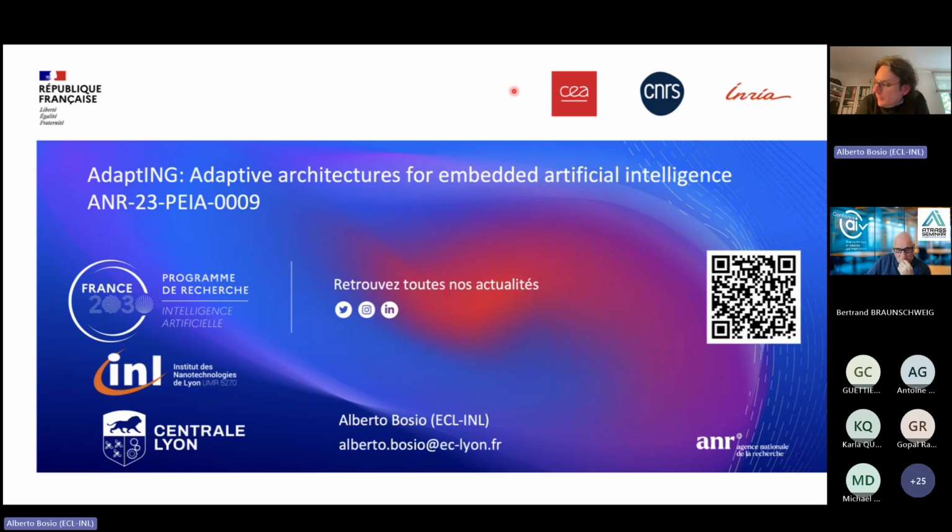Yeah, absolutely, yes. The point is that, to make a maybe stupid example, you can easily triplicate, for example, your complete systolic array, and then vote. But these are clearly at a cost that not all the applications can afford.